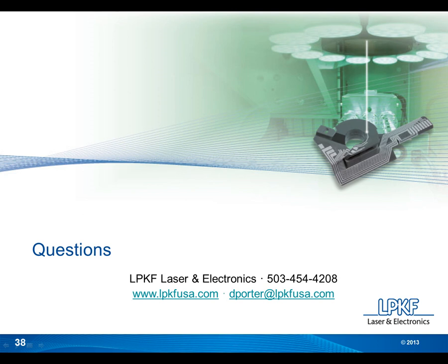And then again, if you want a really high temperature material, then probably you'd be talking about LCP or PEEK, and those type of LDS grades, they're compatible with any kind of solder process out there. Actually, interesting to know, there's new materials that are emerging right now. There's thermoset materials available that have solder temperature resistance like a regular circuit board material. So again, we're even moving to materials that are outside of the regular thermoplastics world, going into the thermoset material world.